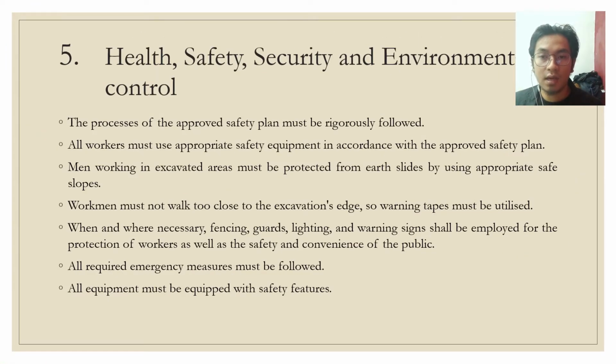The fifth is health, safety, security, and environmental control. The process of the approved safety plan must be regularly followed. All workers must use appropriate safety equipment in accordance with the approved safety plan. Men working in excavated areas must be protected from earth slide by using appropriate safe slopes. Workmen must not walk too close to the excavation edge, so warning tape must be utilized.